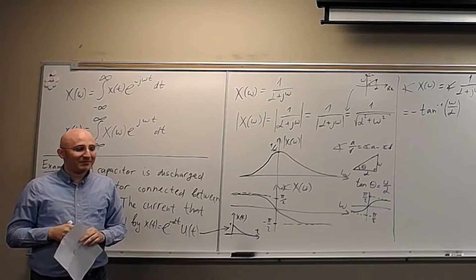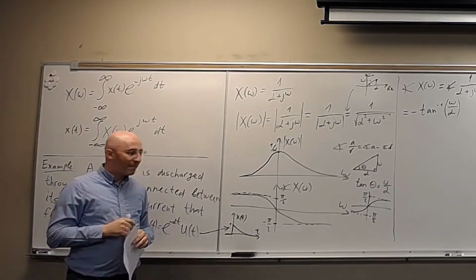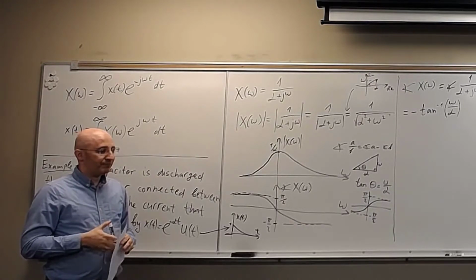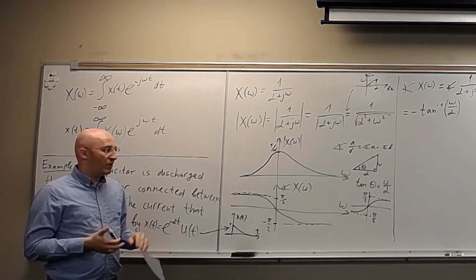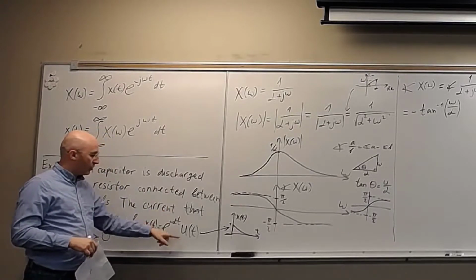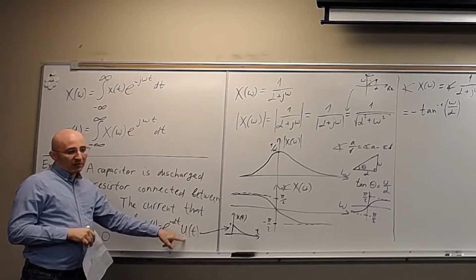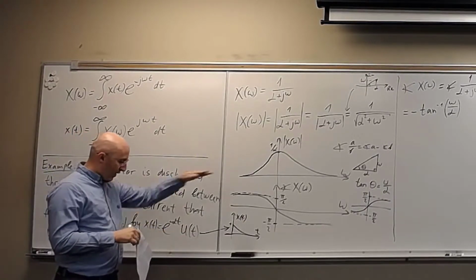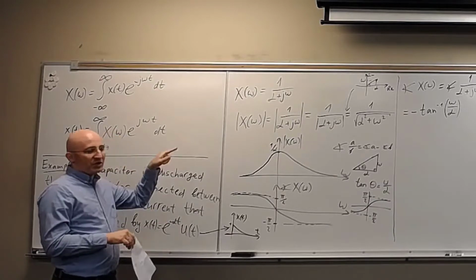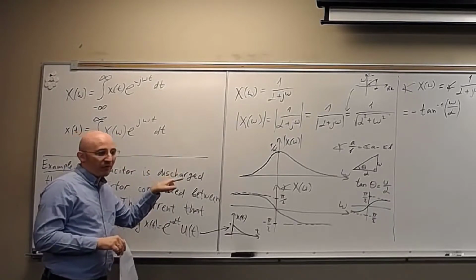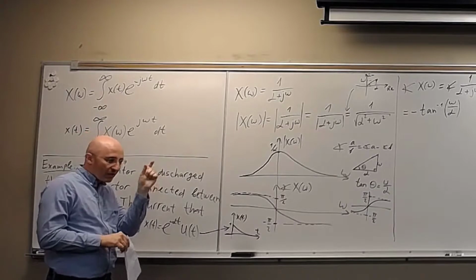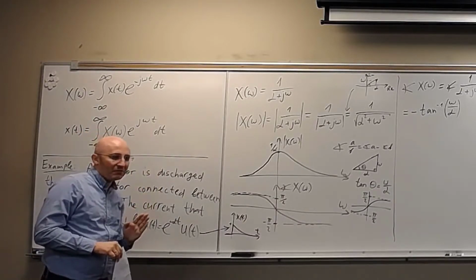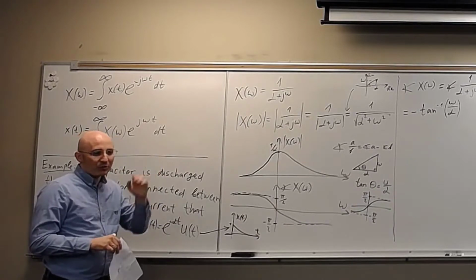So at the areas where there's a quick jump, like at the instant of 0, that's the high frequency, and everywhere else the frequency pretty much is that. Even a step function, if you remove all of that exponent and leave only the step function, will have something similar to that, okay? Because it has flat parts, but then you have a big jump, and in that big jump you need a lot of high frequency to model it in that really short interval of time. So you need very high frequency to show something like a step function, or very close to it, right?